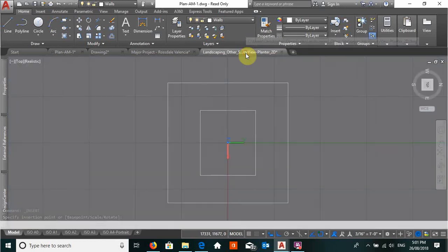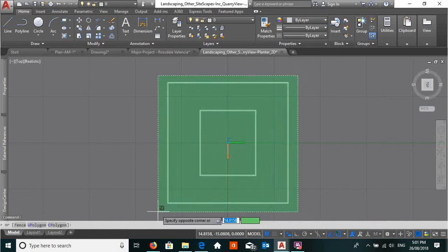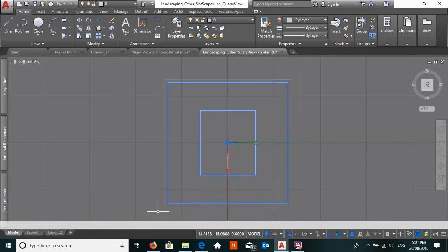If you are wanting to know how to do that with this option, you select the object, and this is what you can do for many drawings. If you want to insert from one drawing file to another drawing file, you literally select the object with the selection window. You go to clipboard, which is in the home tab, and under the clipboard panel you go to copy.